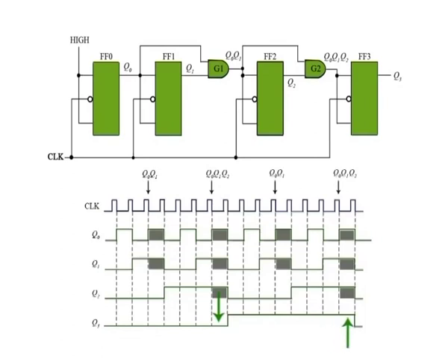Notice that both of these transitions occur following the times that Q0, Q1 and Q2 are all high. This condition is decoded by AND gate G2, so that when a clock pulse occurs, flip-flop 3 will change state. For all other times, the J3 and K3 inputs of flip-flop 3 are low and it is a no change condition.